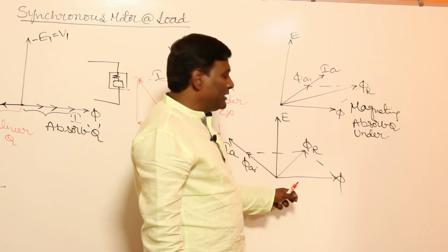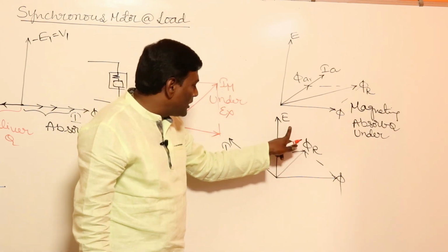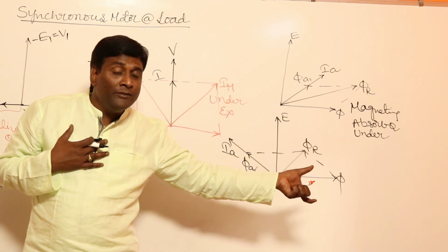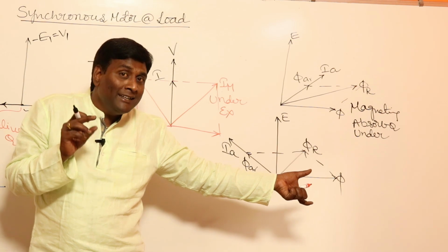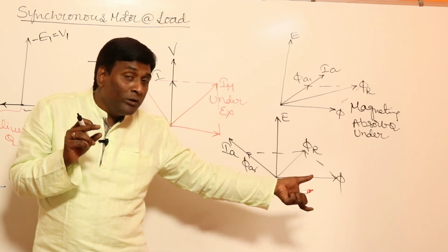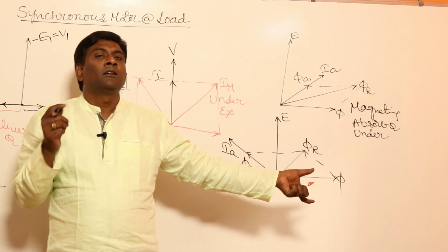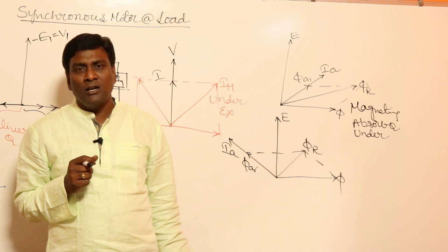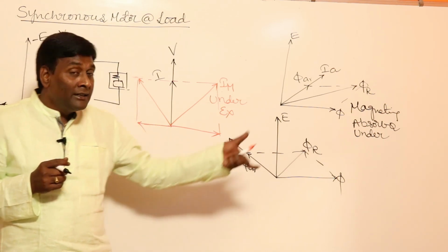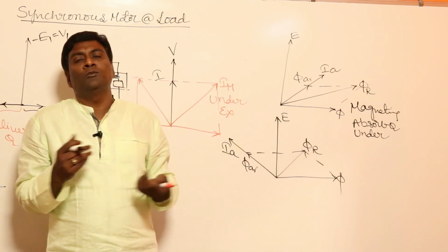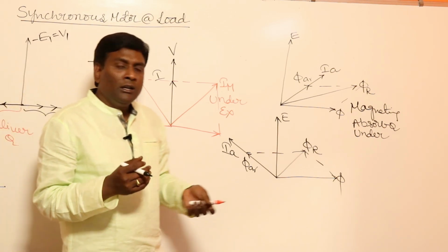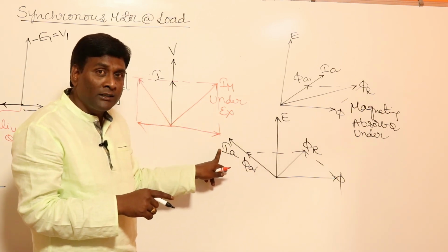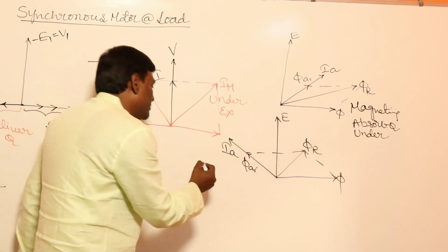Okay, now if you think of a motor operating at leading. For example, I am the generator, that is a load. Now that load is having dominating capacitance effects. The moment the load is having dominating capacitance effect, then only the current will be leading. Capacitor is a supply of reactive power, that is the notation we have been using, that is supplying. Who has to absorb? I have to absorb. So a motor operating at leading power factor, does it absorb or deliver reactive power?